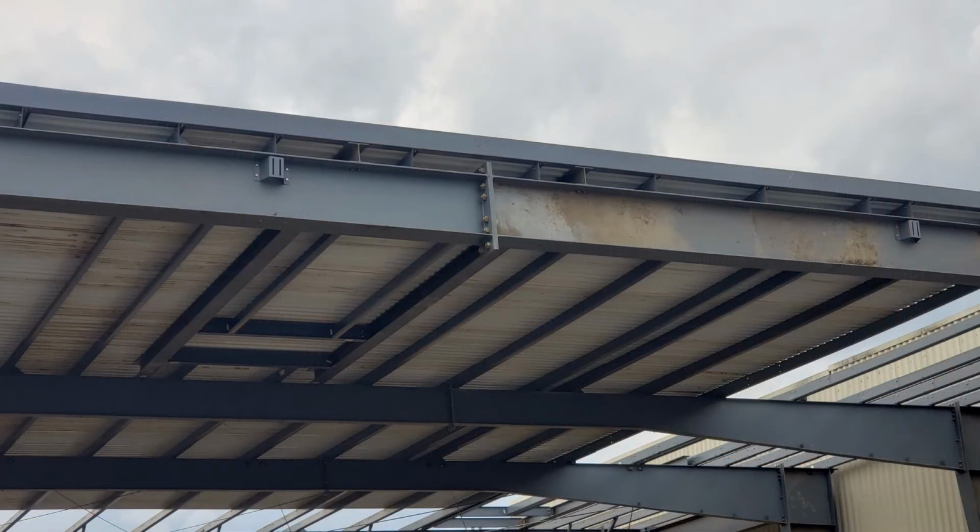So if we zoom in on the roof, you can see that there are cold formed Z-shaped sections. That's a Z-shaped section there, there, and there that form the framing for the roof. Now there's also some hot rolled sections here. Here's a W shape, or maybe it's a miscellaneous, probably W shape. And that frames in this part of the roof here.